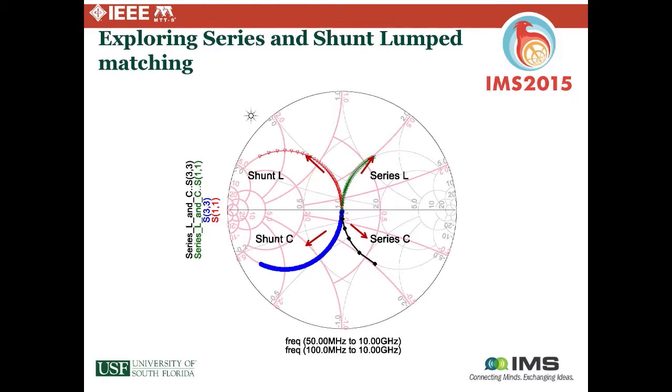Sometimes, and you'll see this in some of the examples, I'm using a standard Smith chart, and you go back and forth between impedance and admittance by flipping 1 over Z, which ends up on the other side of the Smith chart, and we use the same Smith chart. I apologize, that might be a little confusing in these directions, but there are different tools that can be used.